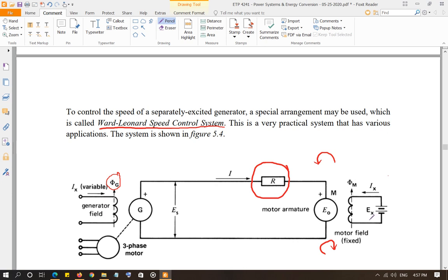For example, in your elevator system, elevators go up and down, that is the direction of the rotation of the motor changing. In addition to that, let's say it is moving in the counterclockwise direction, or the elevator is going up. If you change the direction of the ES source voltage, and current will start going from the bottom instead of coming through the top, what's going to happen? The Lorentz force direction is going to be reversed. And if the motor is moving, since now the torque direction is opposite, it will start slowing down the movement of the motor. And that's basically the electrical braking system.